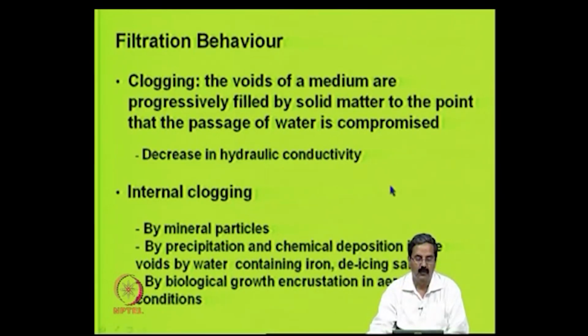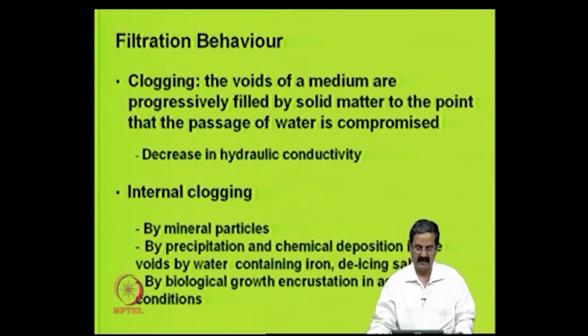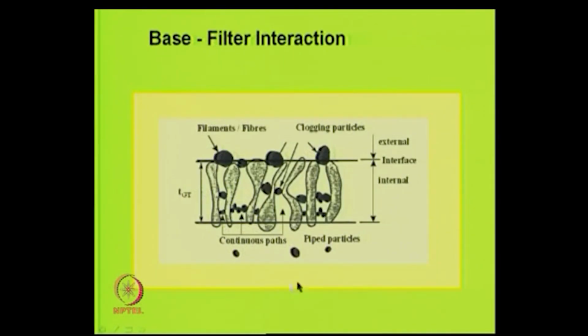So, what is this clogging? Clogging is something very important we should understand, particularly in the case of filters, where the voids are getting filled up by solid matter, to the point that the passage of the water is compromised. So, there is a decrease in hydraulic conductivity. Then internal clogging is also possible by mineral particles, by precipitation and chemical deposition in the voids by water containing iron, de-icing salts, biological growth, incrustation in aerobic conditions. This in a way depicts the base-filter interaction.